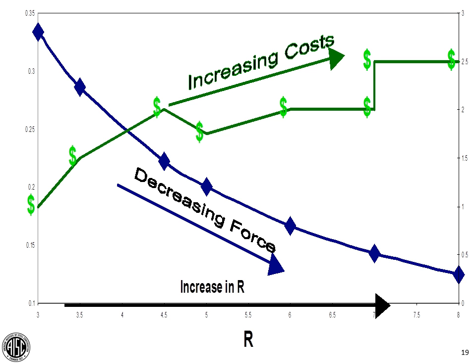So we can see, just roughly for this one structure that was looked at, if we move from an R=3 all the way up to an R=8, like in a special moment frame, we could see 2.5 times the cost. And so you can see immediately the problem that occurs, that if the requirements aren't clear, then the fabricator could potentially end up bidding a job for a fraction of what it's actually going to cost him to fabricate and then to erect this project.